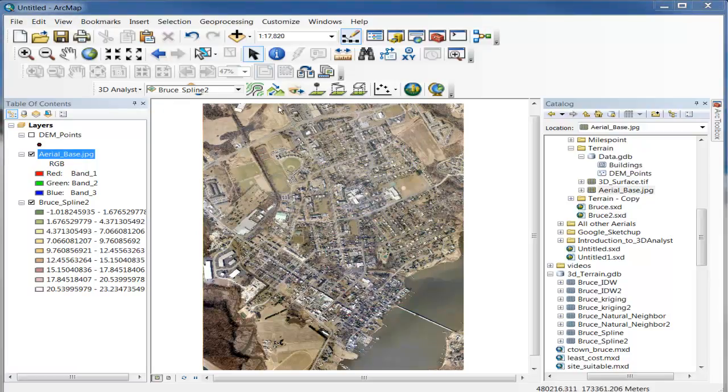Next button we're going to look at is the Create Steepest Path. That's this button right here. You would click this. Wherever you click, it will show you the steepest path. Basically, it tries to get to a lower elevation. It's kind of interesting. You can click it multiple times and it gives you an idea of what the drainage pattern might be for a given area. Again, if you drop it into a sinkhole, it's not going to work very well. Try that across your map. And again, when you're done, you can simply erase them.